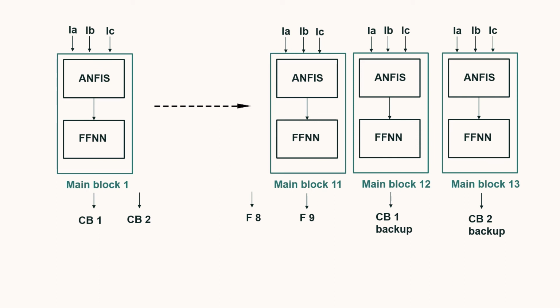After rounding off the output of the main blocks, the result will be 0 or 1. When referring to the current state of all protective devices, an example of a possible state that will come out is 0000010000000. In this case, the 6th digit is 1, which corresponds to the faulty state of fuse 4, because it is still operating even though the fault has happened.